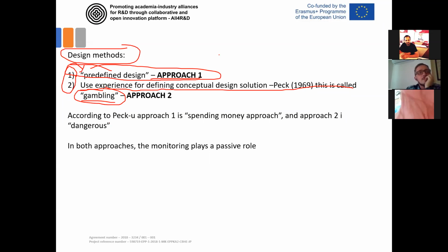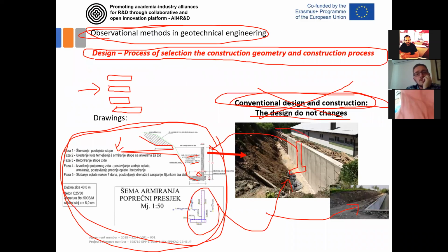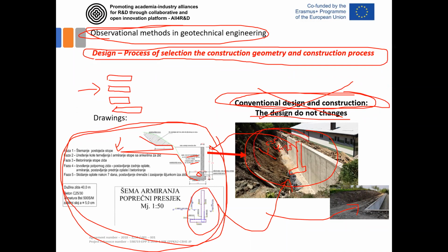What is the problem with this approach one that may be considered really appropriate and correct? The problem is that it can sometimes be a more expensive approach. What does it mean? It means that for this wall, for example, I could say, okay, I won't do any investigation works. I'll just check the condition of this soil. I'll say, okay, it may be some C5, it may be some soil C23, and let me design this wall: the sliding stability, overturning stability, bearing capacity, global stability, and it will define some wall that has the geometry like this.